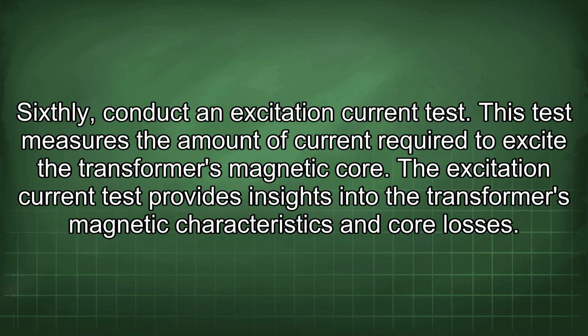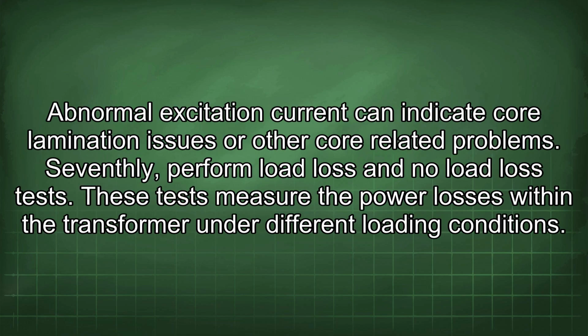Sixthly, conduct an excitation current test. This test measures the amount of current required to excite the transformer's magnetic core. The excitation current test provides insights into the transformer's magnetic characteristics and core losses. Abnormal excitation current can indicate core lamination issues or other core-related problems.